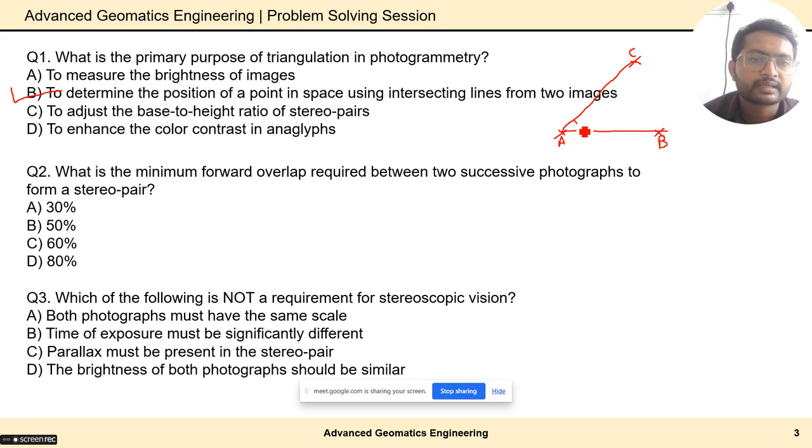This angle we name alpha, and this angle beta, and then we use trigonometry to find the distance between points A, B, and C. So we know this distance d in triangulation. Basically, when the data related to 2 points are given, using angles you calculate the distance with reference to the third point.